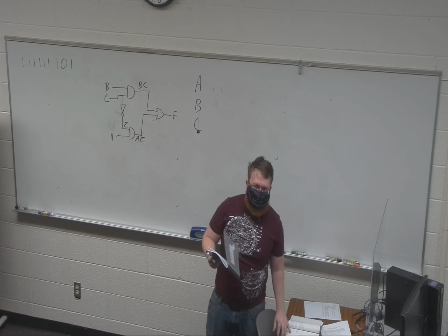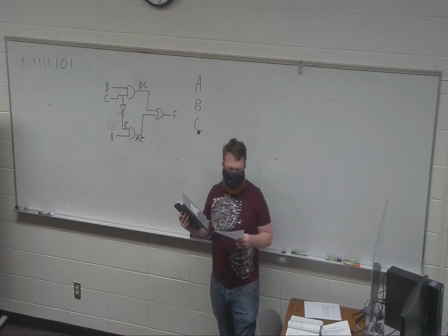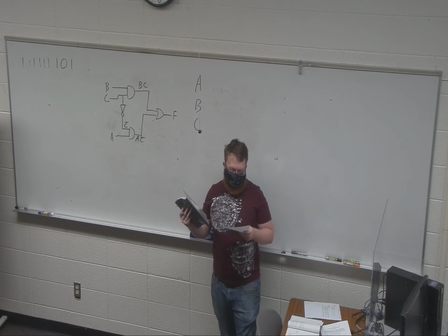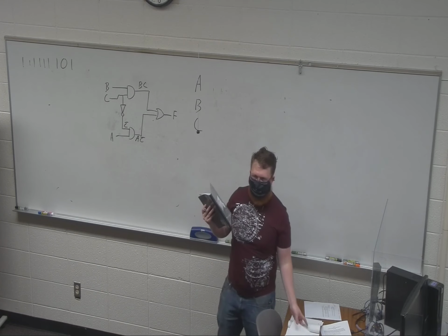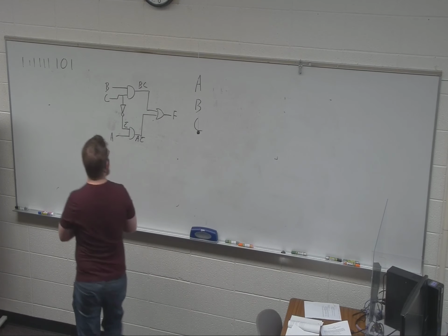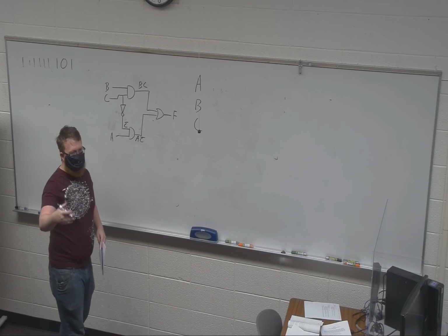A glitch is what's going to happen in sequential logic, similar to our hazards earlier. This is really kind of a hazard slash glitch. Glitches happen repeatedly and predictably on a clock, essentially, is what you're looking at.